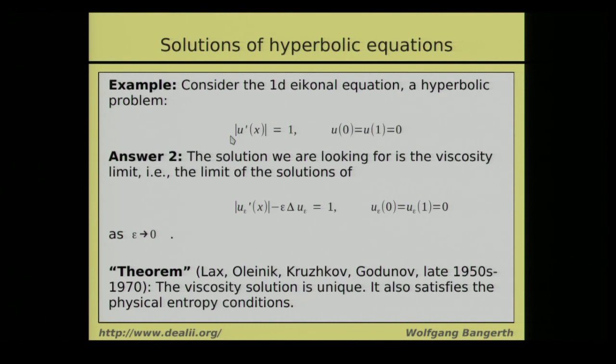So this is a deep result. This is not trivial to show. But it gives us a little bit of an approach for how we can solve these sort of problems. Namely, when we have this transport equation, for example, and we see that we have all of these oscillations, then one of the solution approaches might be that instead of discretizing the original transport equation, we should discretize a variant of it where we add a little bit of viscosity.